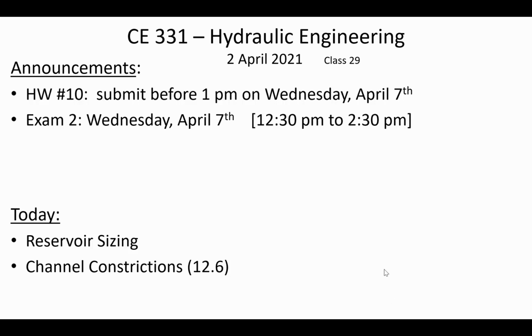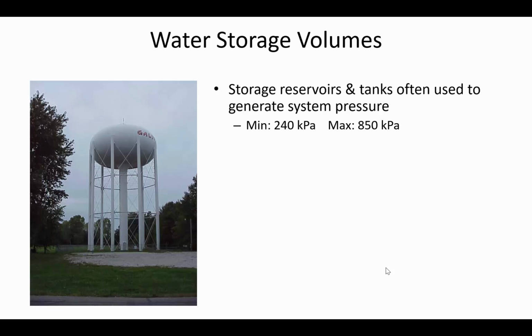Let's talk about reservoir sizing. We have a reservoir in the project because we want to, number one, pressurize the network. You can pressurize a drinking water distribution network with pumps, of course, and in a lot of flat places that's how they pressurize the water network, is just have a pump operating at all times, and that adds pressure and the water can be withdrawn from people's faucets. And the other way to do that, though, without requiring any electricity, is to have an elevated storage tank.